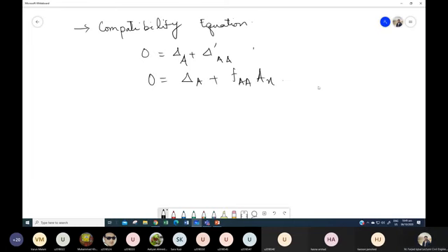So for the virtual work method, you remember that the equation for the deflection is the integral from 0 to L of capital M, and if I revise this one, this capital M is the moments that are acting on the frame when all the external loads are acting. And this small m is the equation of moments for the frame when the virtual load of one is acting in the direction of desired displacement.